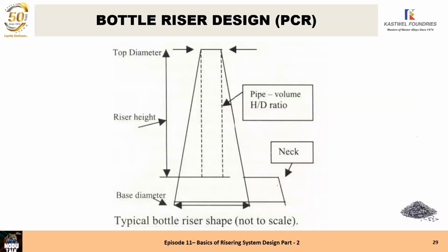Now we'll talk about the bottle riser. We have completed one design of the riser by the pressure control method. Bottle riser is another design which I prefer as a pressure control method. This figure is not to dimensions. This is just to indicate the important parameters in the bottle riser design which we have to consider during the dimensioning of the riser. At the top, we have got the riser diameter.